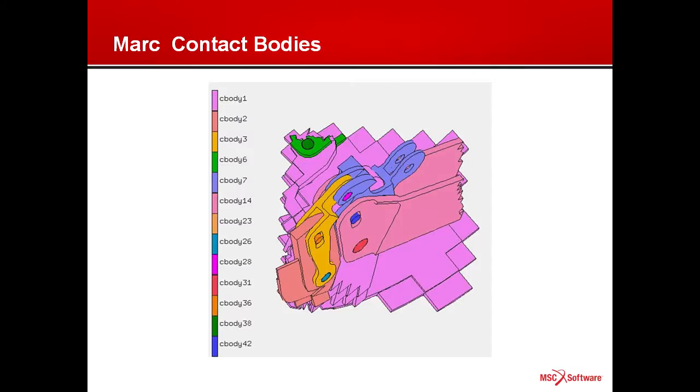Contact bodies, again, Marc, even in Nastran, because we have this contact bodies, every one of these colors is a contact body. We don't care about the elements. We'll figure out the contact faces or the element faces. This greatly improves and speeds up the NVH process if you have to do these door latch. This is one example, or gaskets and so on.